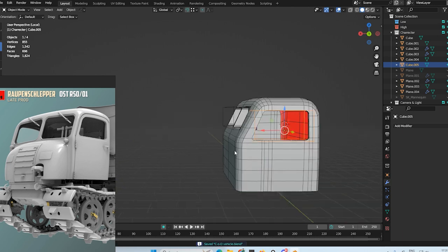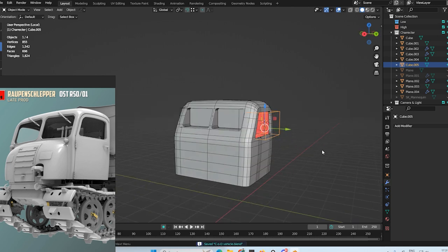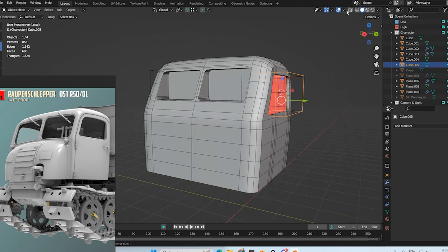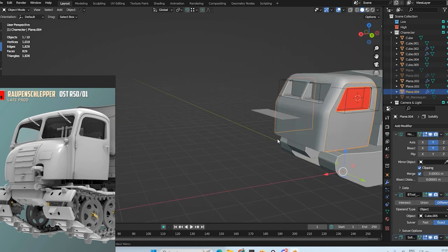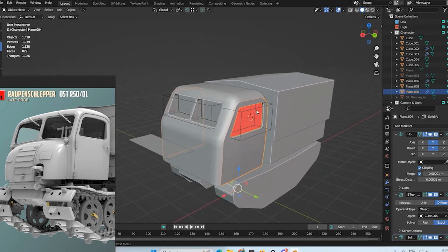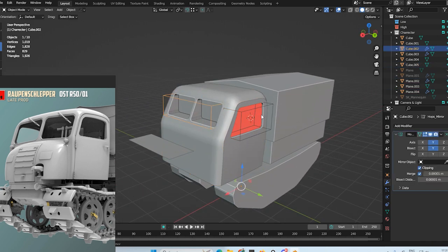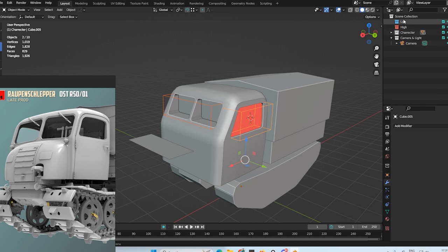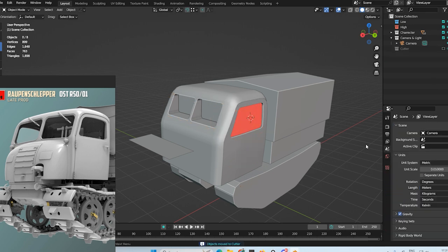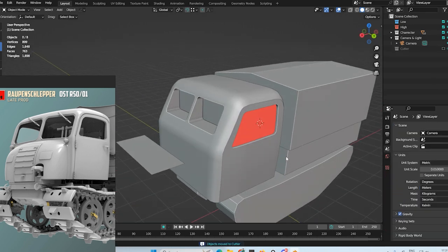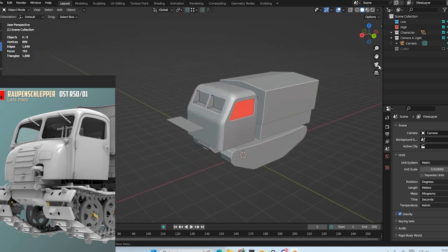Now I turn off the wireframe because I want to see how it looks with our other shapes. I create a collection called cutter, where I place all the cutters in this folder and turn it off to see things clean. Always organize our files.